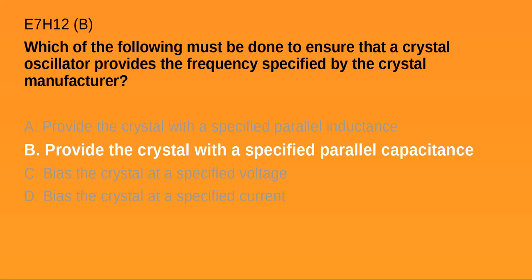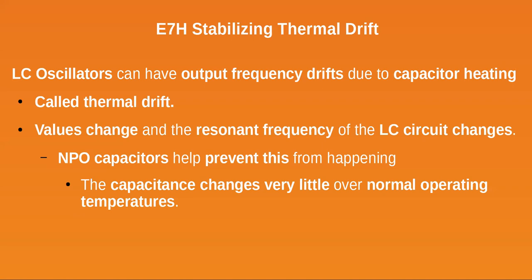You can actually shift the frequency a little bit by varying that capacity. In fact, you can make it somewhat a tunable oscillator by using a varactor in parallel with it. So that's what the old novice radios did, that were slightly tunable. You can't move it much, but you can shift the frequency. We're still using a crystal. Yep. Or you can heat it up, but you have a lot of control.